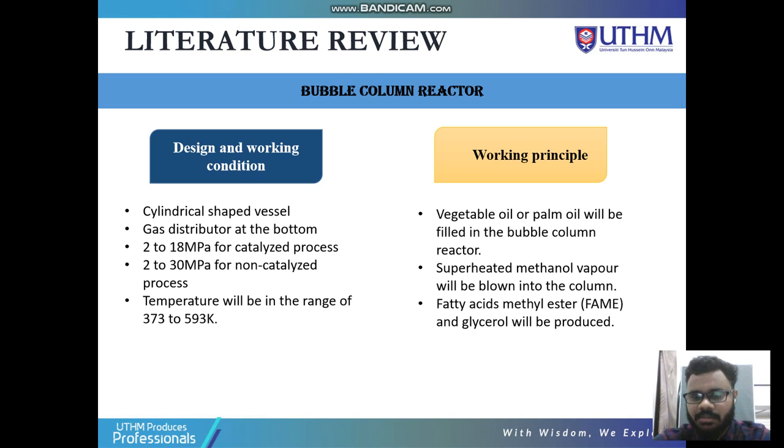Okay, what is the working principle of the bubble column reactor? The vegetable oil or palm oil will be filled in the bubble column reactor earlier, and then superheated methanol vapor will be blown into the column. This will produce a fatty acid methyl ester, which is the FAME, and also glycerol as the byproduct.